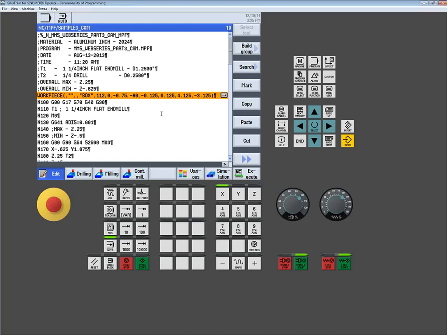We suggest if you're going to get into that technology of a machine that you modify a post so it can run in the Siemens world. The other thing is, this is kind of our world. When you get to 5-axis or mixed technology, mills that do turning or lathes that do milling, this is where Siemens really starts to shine. This is why you would want to buy a Siemens control, because this is our world. We live in this world. So with that being said, if you try to start running the system in an ISO mode, potentially you can give yourself a lot of pain, and you're not taking advantage of all the functions that are there. So be careful.